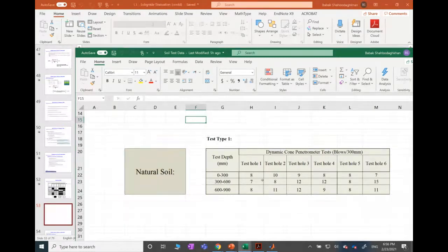We can consider, for example, 50% as a boundary of the fine material or coarse material. But for the table that I showed you, the value is different. So this depends on the behavior during the tests they have conducted. For the road, when they wanted to classify the materials, they use this one.